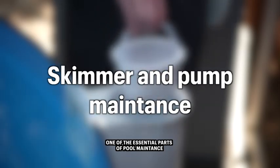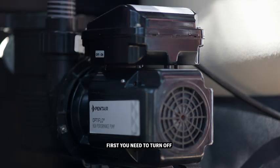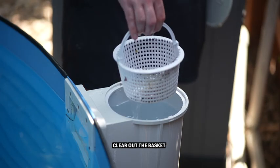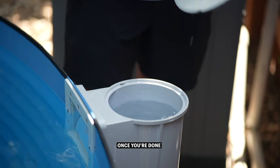One of the essential parts of pool maintenance is clearing out your skimmer and pump baskets. First, you need to turn off the pump and then close the valve located on the suction side of the pool. Then you are safe to open the skimmer lid and clear out the basket. Don't forget to put it back in once you are done.